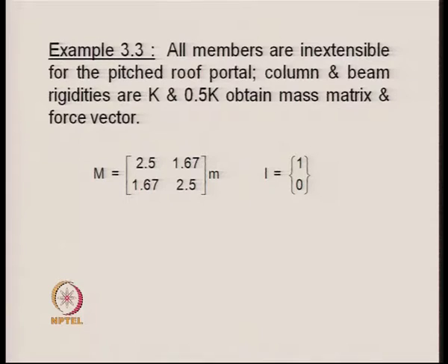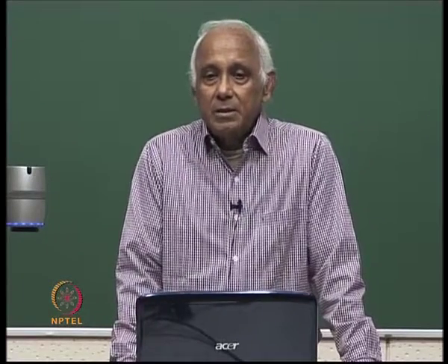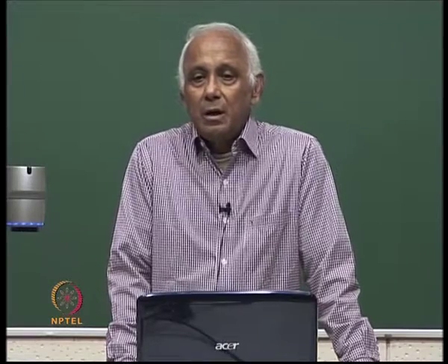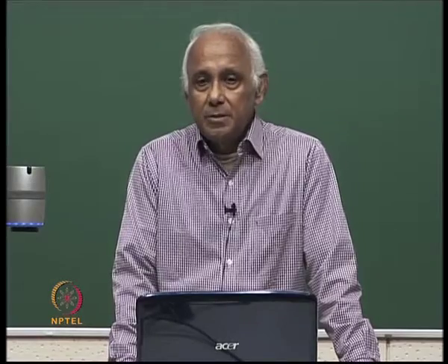After that, we discussed the equation of motion for a multi-degree of freedom system, in which we classified multi-degree of freedom systems under two classes. The first one was single support excitation, and the second one was multi-support excitation. For the single support excitation, the base of the structure moves as a rigid body.